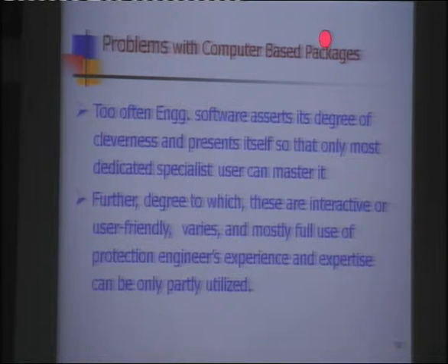In the research work, it was observed that it was possible to add only 9 single line out contingencies out of the 41. Then we observe by experience how many of those lines are important, and then we sample relays. So this is regarding the setting of relays to provide the optimum protection.